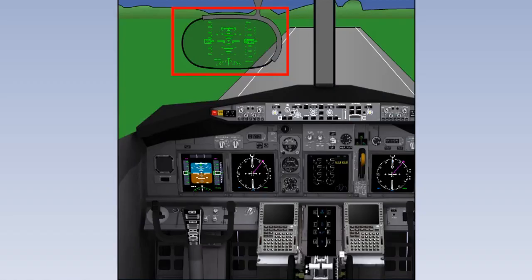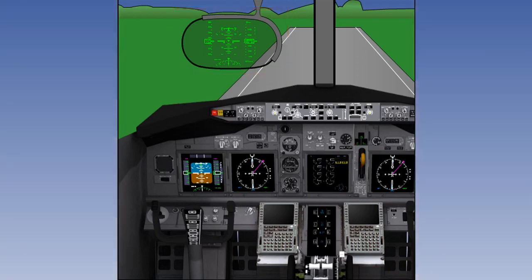The final group of terms relate to aids to completing an approach visually. Here we will consider the head-up display, the HUD, and the Enhanced Visual System, EVS. A HUD will project flight information onto a transparent screen in front of the forward cockpit window, such that the pilot can see vital flight information while also looking ahead for the specified visual reference to complete the approach. This system minimizes head movements and also reduces the chances of becoming spatially disorientated.